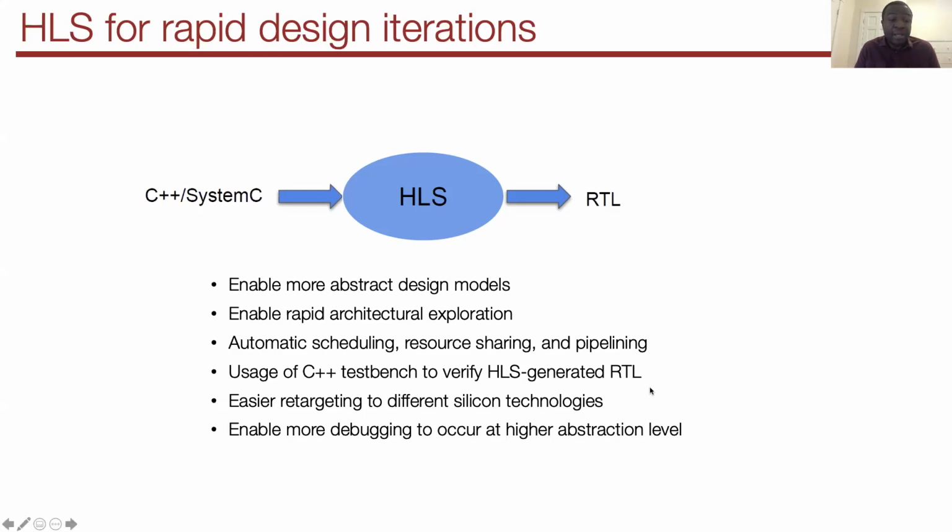HLS also allows for easy retargeting to different silicon technologies. And when it comes time to debug the hardware, most of the debugging happens at the abstract C++ level as opposed to debugging at the RTL level.